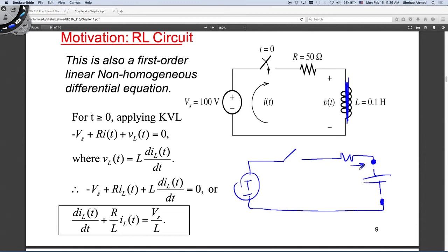Here current does not flow anymore. Here current flows, but voltage is equal to 0. Here current does not flow, but voltage is equal to some value Vc, right? Because you've charged the capacitor to a certain voltage level. Okay, do you see the difference between capacitors and inductors? That's steady state. So in the transient, current will maybe start from 0 and then rise all the way until